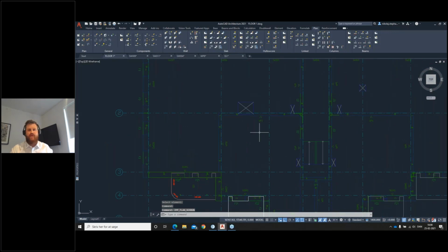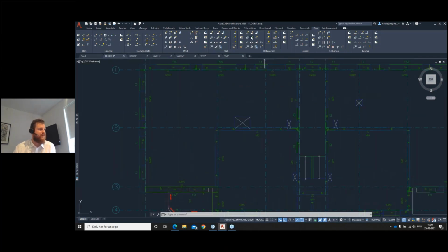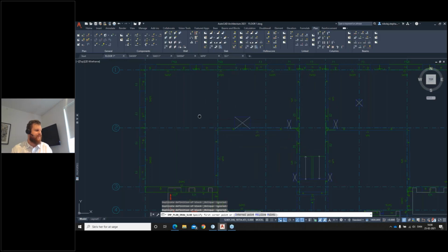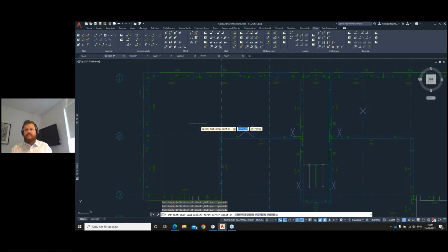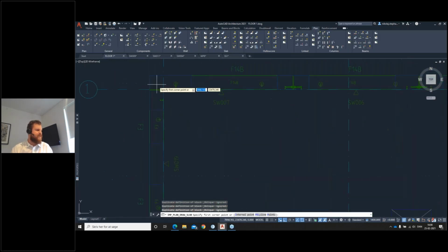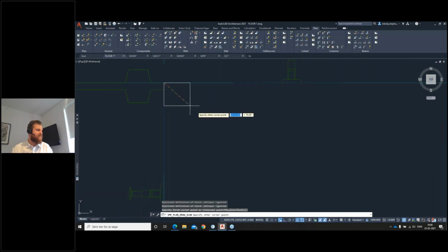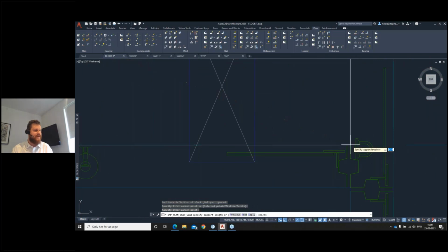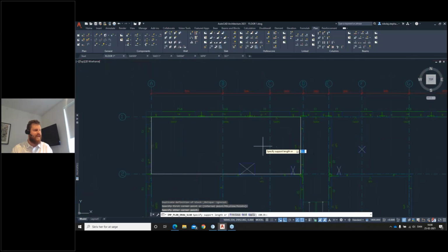Jumping back, as I promised you a lot of things in a relatively short amount of time, I want to do some hollow cores as well. So I'm selecting my different definition of hollow core here. Basically, this is a section, so any hollow core you have, you can just add it to the software in here. Here we can draw with windows, with polylines or points. In my case, let me just take a window. Let me just see if I can snap properly. Notice that I'm snapping on the insides of the element, and then afterward the software asks me about a support length.